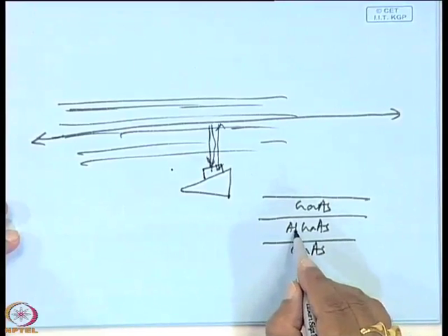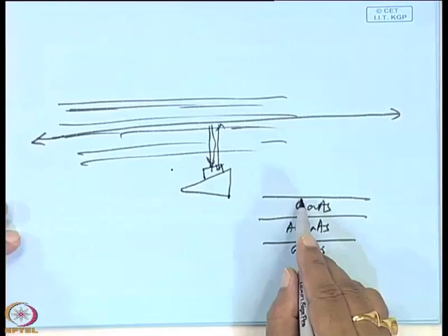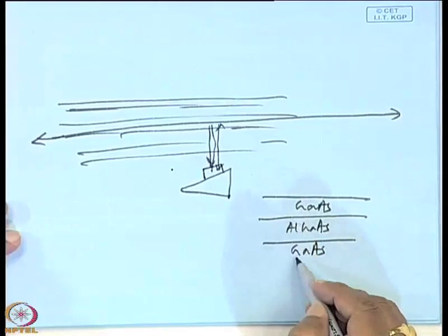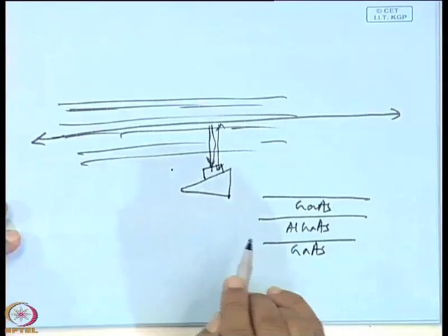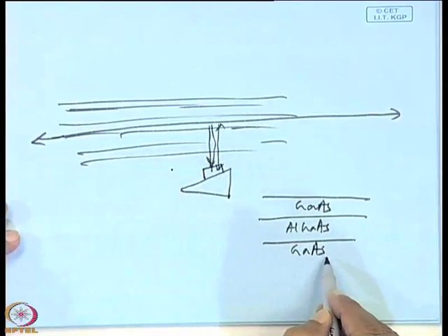Okay. So, now out diffusion means here aluminum from the second layer can diffuse to the layer above or the layer below it. So, that is out diffusion, or from the substrate some impurity can diffuse to the layers, that is auto doping.